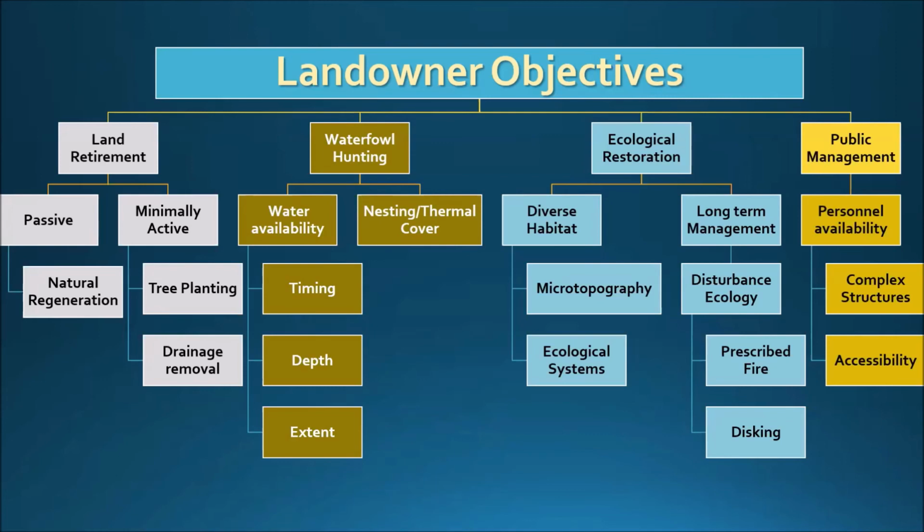But if a landowner is interested in something more specific, say waterfowl hunting, or that second column, the site must be reviewed even more thoroughly. Will water be available at the right time of year to attract the birds? Will it be deep enough and not too deep to allow the birds to forage? Can the species access their food source? Is there thermal cover? Nesting cover in spring if that's a target. What would be the impact of any enhanced hydrology on the existing vegetation? Some landowners have requested to flood forested areas, but that is a detriment to the trees.